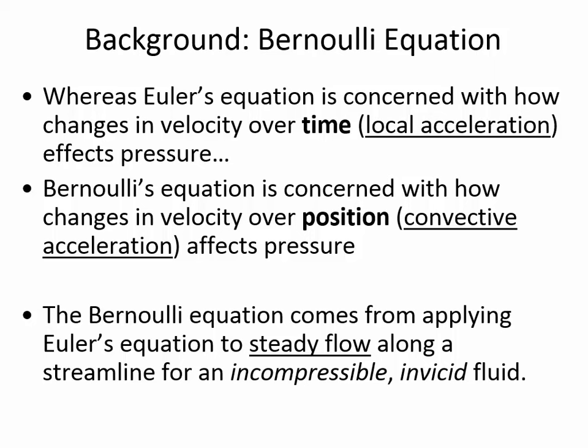And so liquids are relatively incompressible. So what's a gas that fails the incompressibility test? Air, nitrogen, helium, gases. And so what this is saying is Bernoulli's equation is pretty good as far as the incompressibility assumption goes. It's pretty good for water, not so good for gases, because gases are compressible.